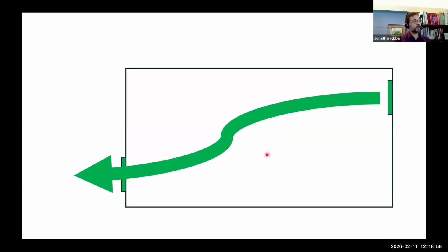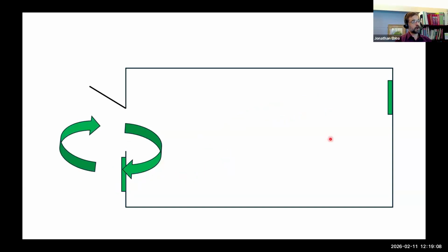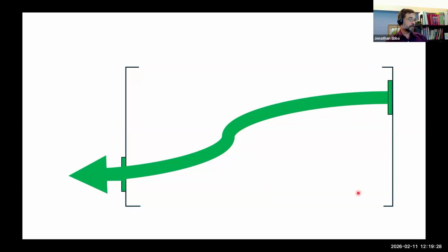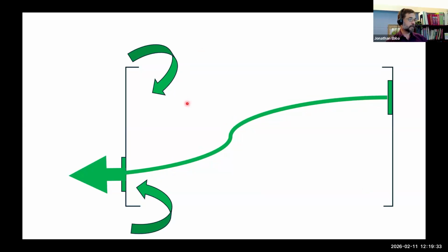If we are doing an exhaust fan here, this is what I was talking about, making sure that the open door isn't on the exhaust fan side, because we just end up with this, and we aren't pulling the air from here anymore. Air's lazy, and it's going to take this short route instead of this long route. And likewise with our roll-up sides. This is the one we see sometimes where we're just wasting our electricity. If the exhaust fan is running and we roll up those sides, same deal. The air is sneaking in around here because it's lazy, and it's not being pulled through the house.